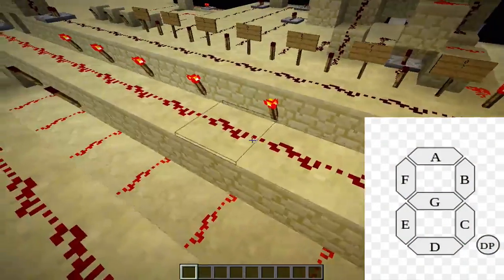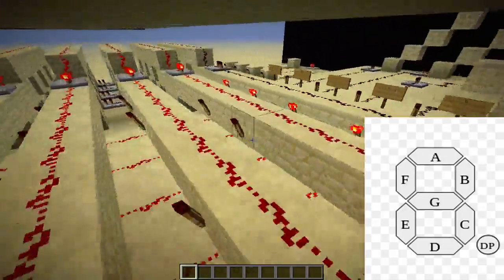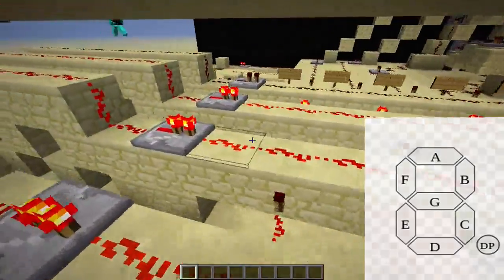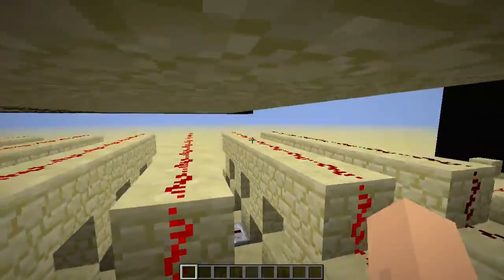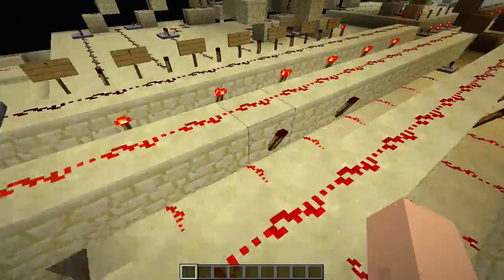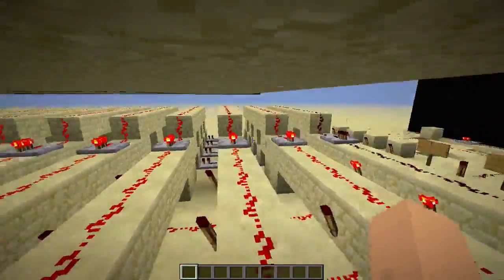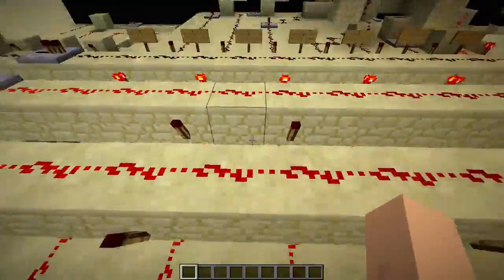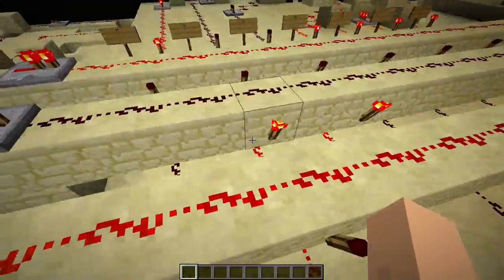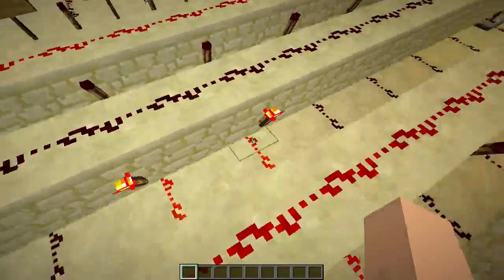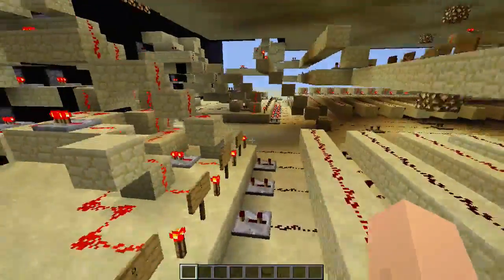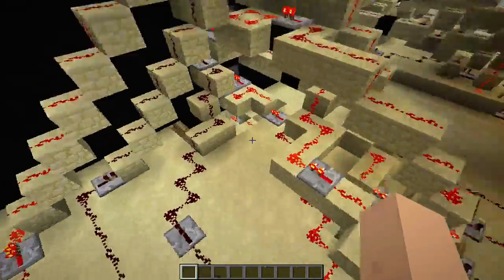And you can see now for number 1 as well, we have segments B and C turned on, only for number 1. But right now, the binary digit 0 is selected, so everything else is disabled. So whatever binary number we put in, we'll get out the proper 7-segment value. And you see now Jans has selected number 1, so now this is showing the 7-segment digit for 1.